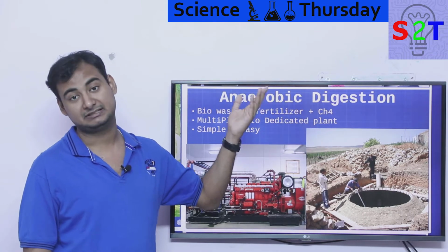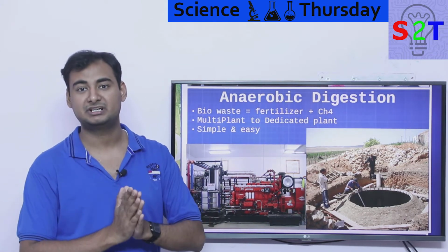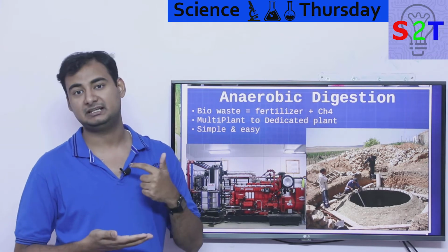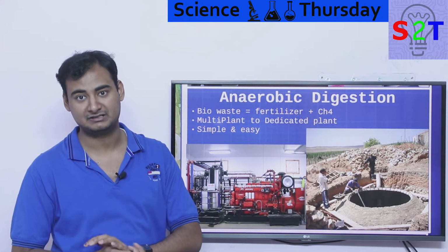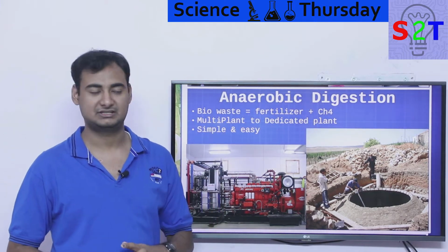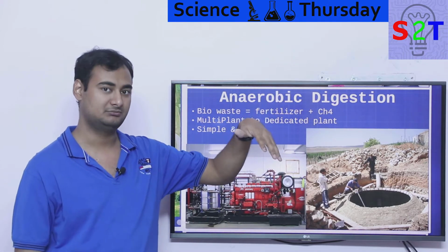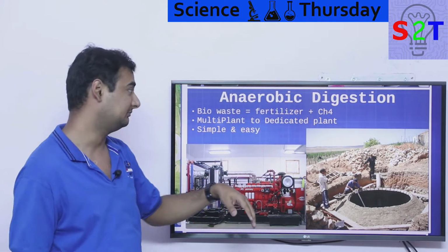So we take it, and thankfully, even though it's very hard to store, in the sense that you can't store it volumetrically efficiently. It's not a liquid fuel, and it's not propane or butane, where you can compress it efficiently. That's why a tank that can, quote unquote, liquefy CH4 is very expensive. So we generally store it volumetrically, basically just build a very big tank, as big as you can build it.